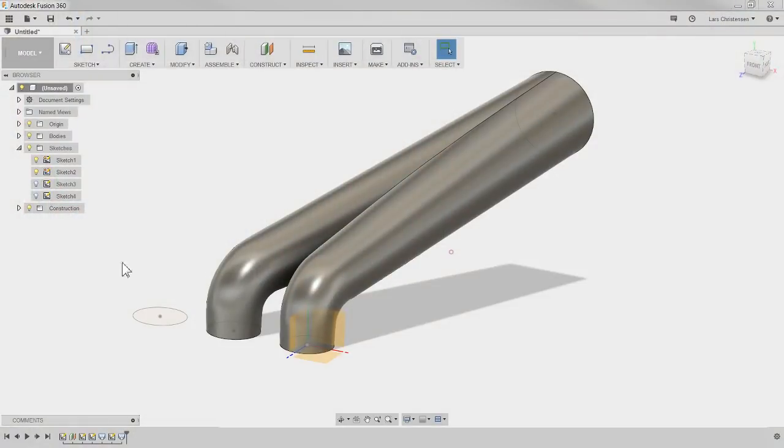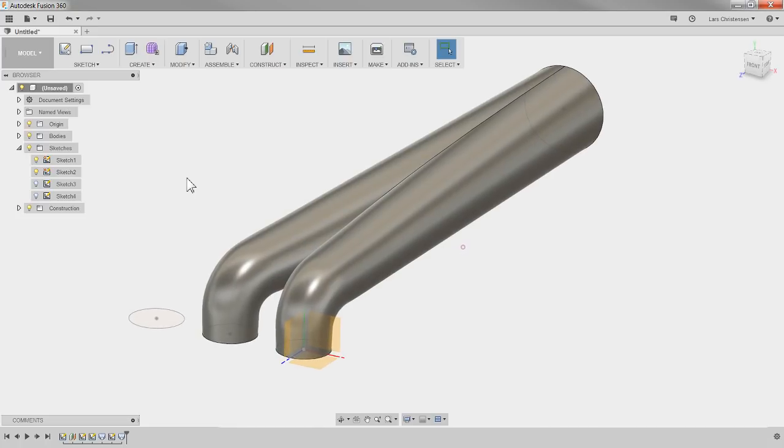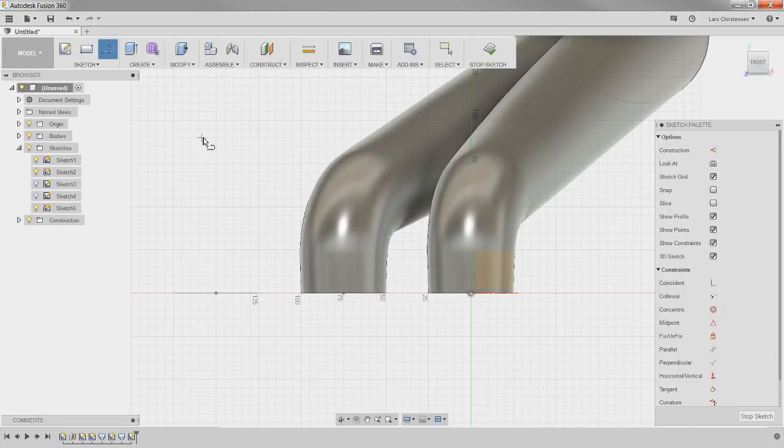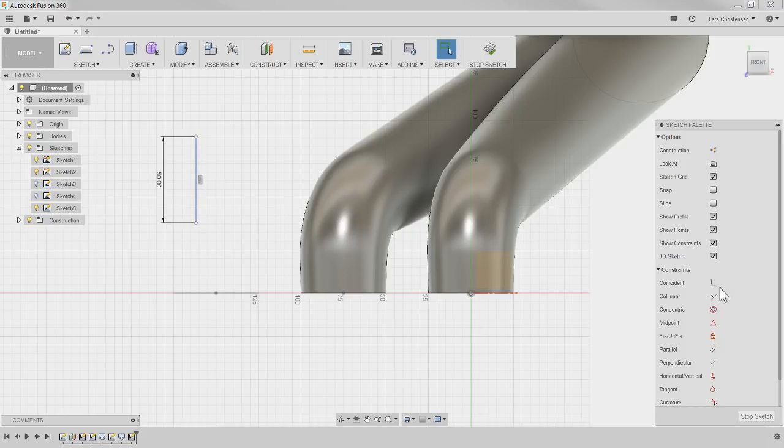Let's do one more. You let me know. Thumbs up, thumbs down. Let's open up one more sketch. Finish the last one up here on the same plane. Hit alpha line again. I like to type in 50, tab, so that distance is locked in. Hit enter, and then make sure I get the vertical relationship. And then we can lock that into there.